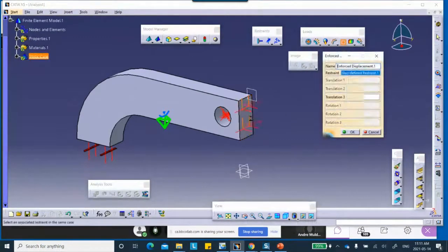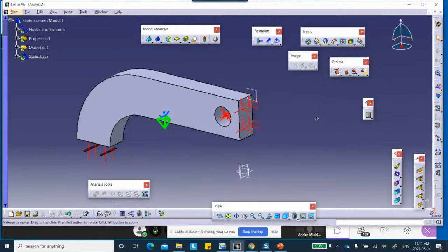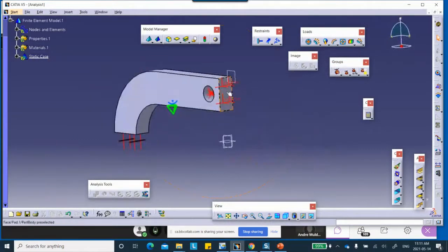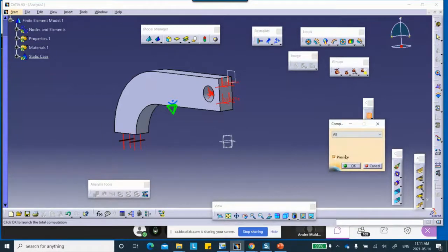This is the restraint. And it was not negative, because for this part it's going to be plus, right? We're going to push it up. So 0.01. Good. I put all my surface sliders. I put the load. This is called a load, because when you're moving something by 0.01, you must have applied a load. That's why you see that displacement under the load icon, a toolbar.